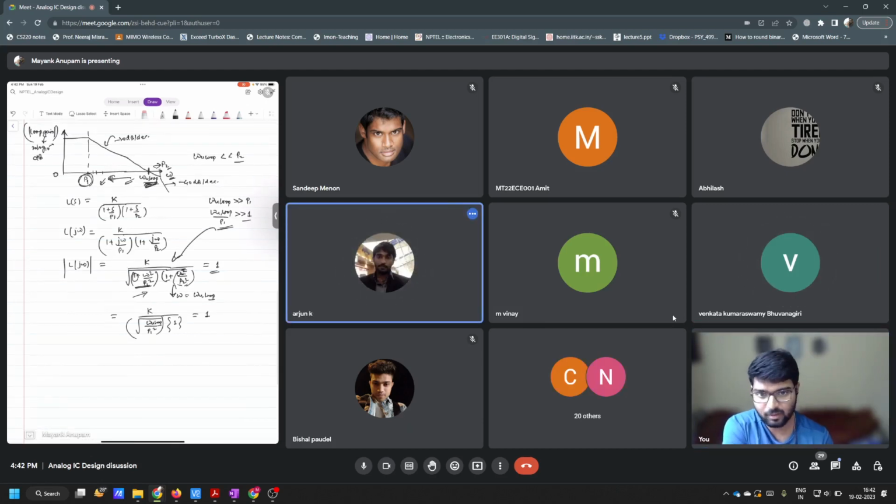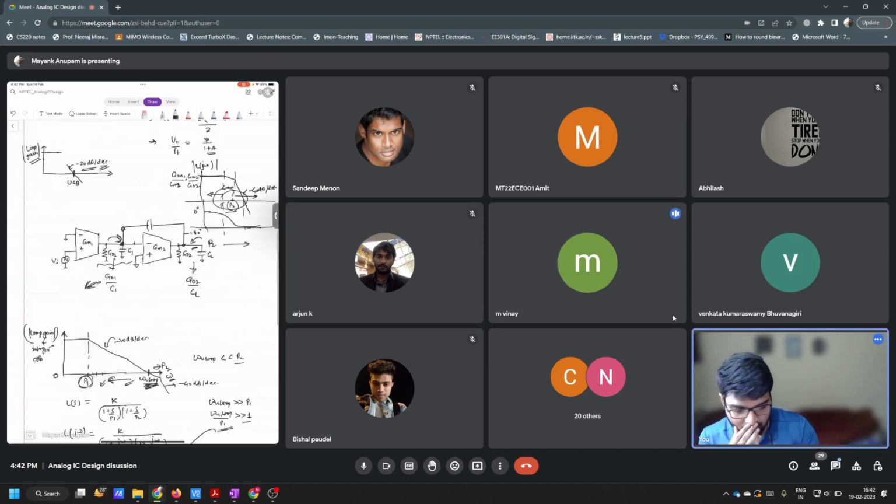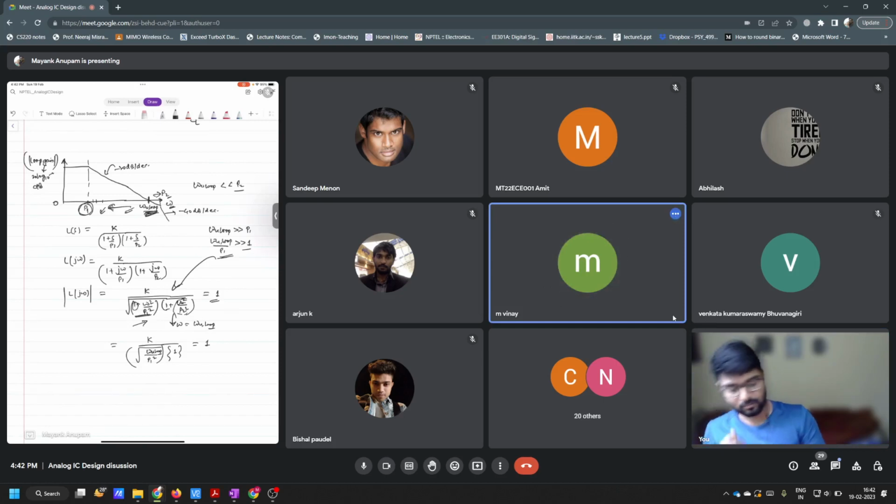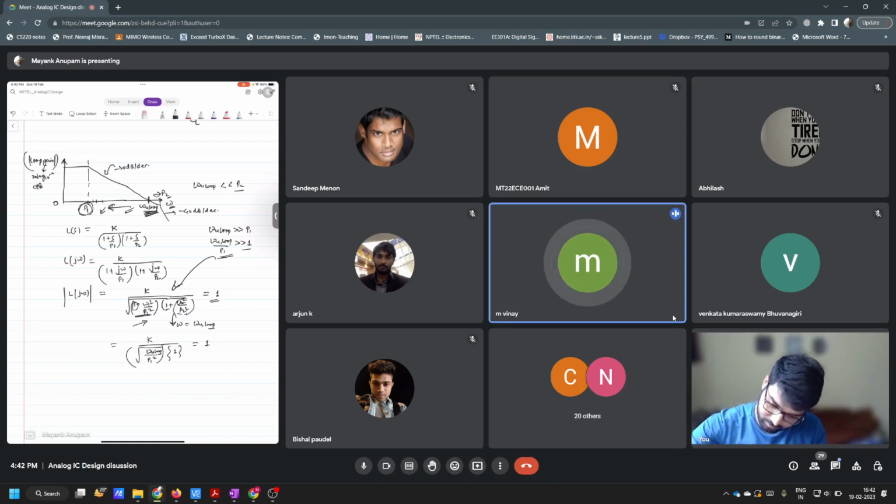Yeah, it's the same thing. Hello, sir. I have one doubt, sir. According to bandwidth, it is where the gain decreases to minus 3 dB, right? So that is true. In a dominant pole system, P1 will mostly be that bandwidth, no, sir? Because at that P1 only, the gain decreases to minus 3 dB.